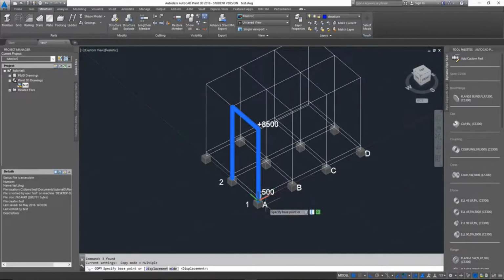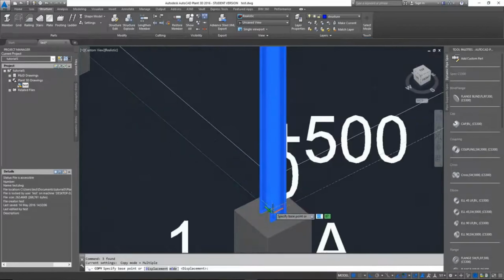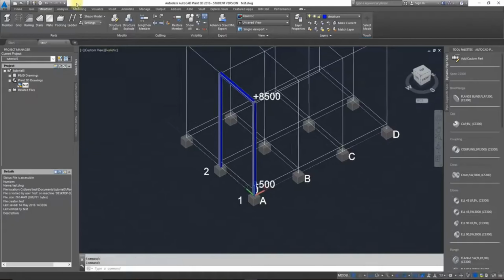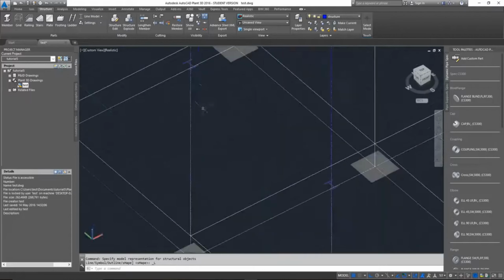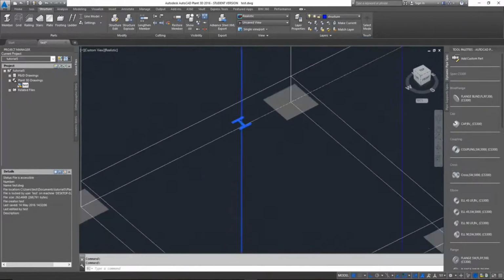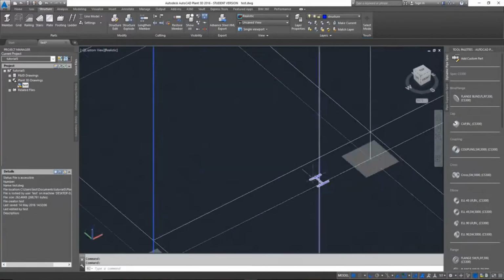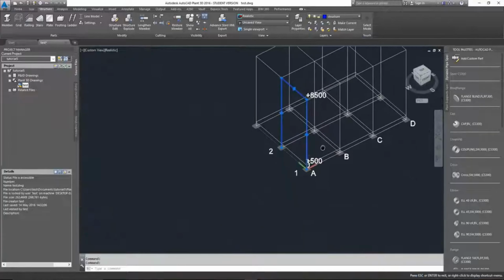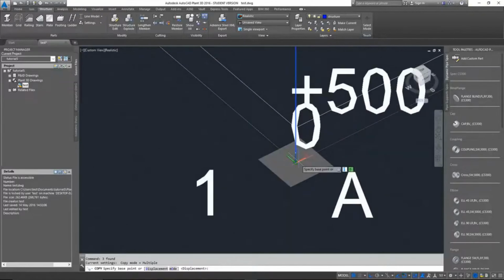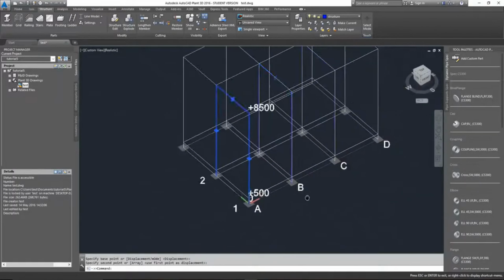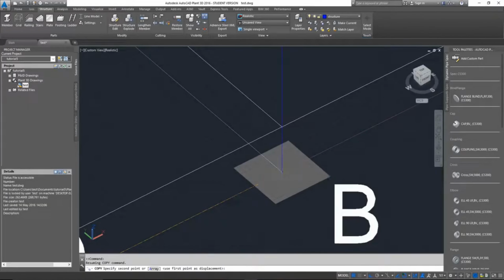Okay, so again, I have selected them. Press CO. Oh, see, here's the point. Now if I were to select a point, I can't really tell if it's the exact grid point or what I am selecting. So that's why it's always beneficial to go back to line mode. Perfect. So now I can still select my structural members by clicking on those. I have selected all 3. Perfect. Now I'm going to enter CO. Copy is going to ask me to specify the base point. Now I'm going to specify this base point. Okay, perfect. Now I'm going to copy it 3 times.